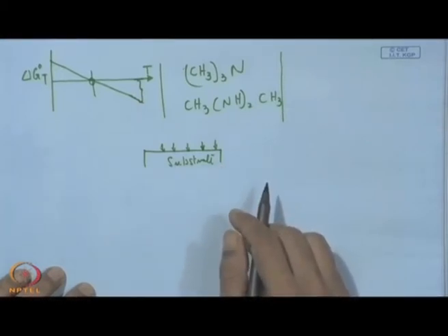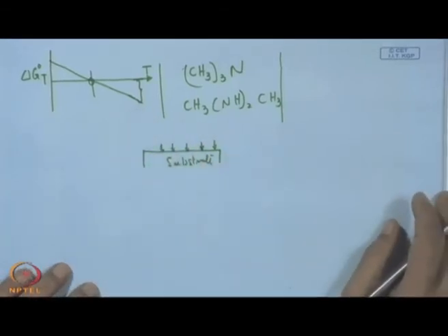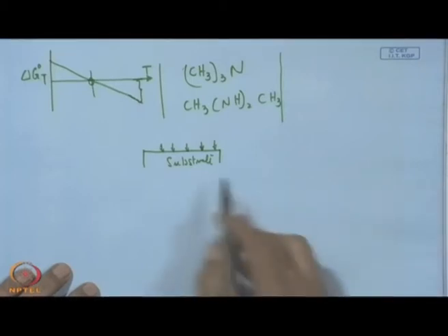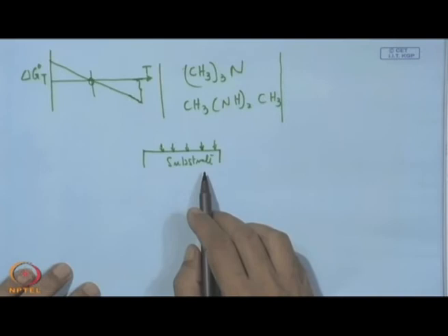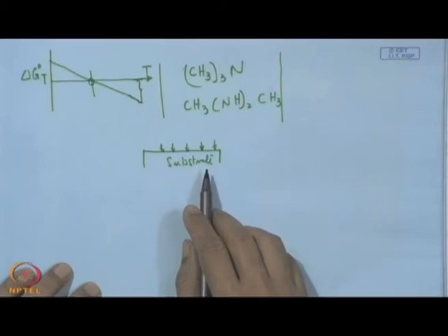But as we have mentioned, if we go to that temperature, that may be counterproductive in that the reaction may no longer be heterogeneous, but it becomes homogeneous, and then the whole purpose of CVD is lost, because in that case the gas phase reaction takes place and we get dust, powder, flakes of titanium carbonitride instead of a uniform, well adherent, well coherent coating on the substrate surface.